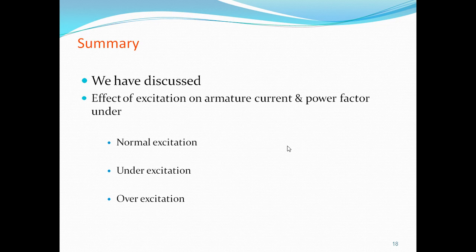So when excitation is changed, the magnitude of induced EMF EB changes, whereas the load angle alpha remains constant as long as the motor load is constant.